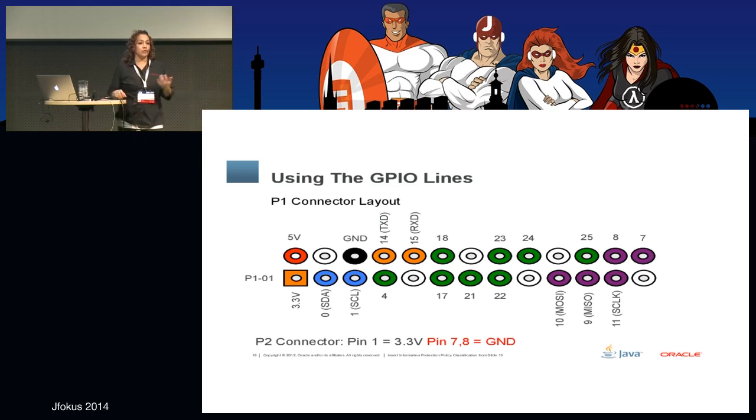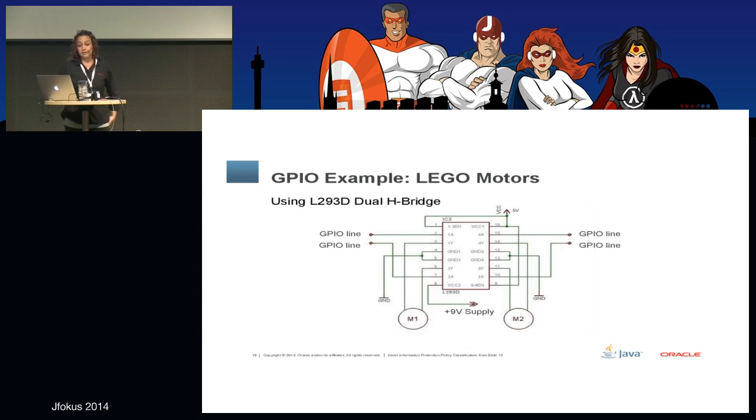And again, I was trying to do my code and I was, okay, GPIO pin 17, true, nothing. 17 true, nothing, and it ended up being actually 0 for Pi4J. So just make sure the numbers of the pins are different, but again, it's the only thing to be careful about. And connecting a motor to the GPIO lines is extremely simple too.